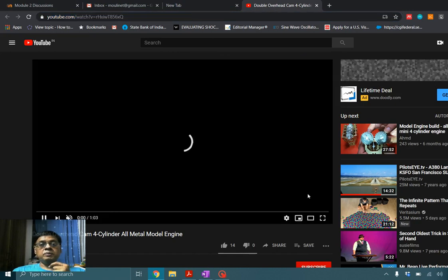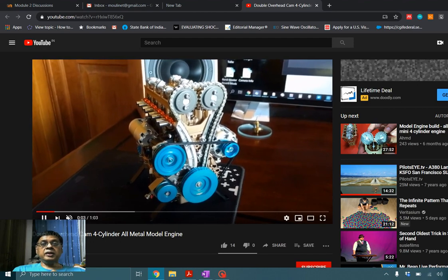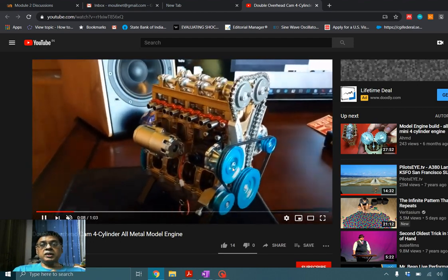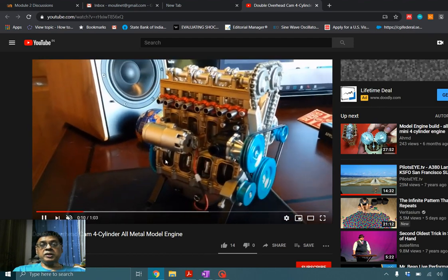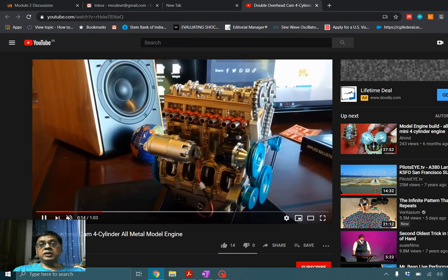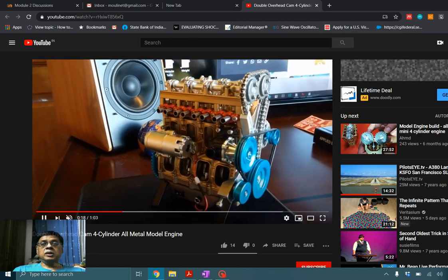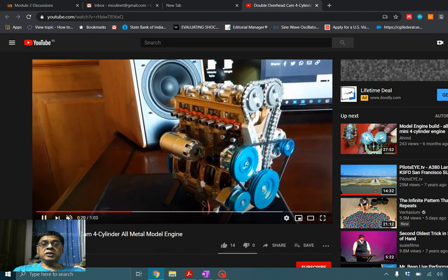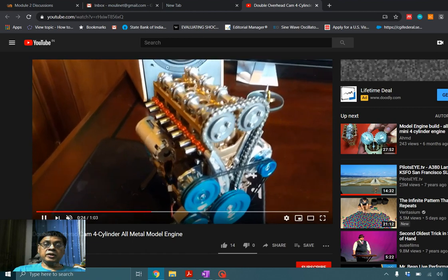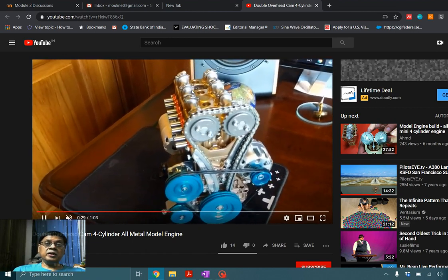Okay, skip ads. So you can see here, this is the drive. That camshaft is on top. The drive is coming from the crankshaft, which you can see here. This is the crankshaft, and from the crankshaft output through this is a timing belt. So you have a 1:2 reduction that is going to be here. This is a toothed timing belt. So we transmit from here to here, and then we basically achieve the reduced speed.